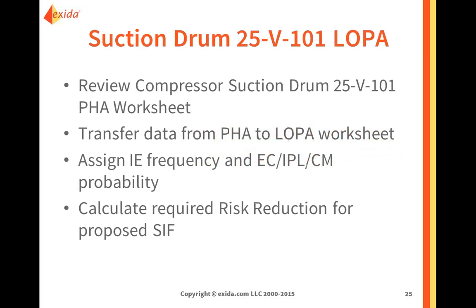So that's an example. Let's look at the layer of protection analysis tool in action. What we want to do is look at what I just showed on the slides: review the compressor suction drum PHA worksheet, then transfer the data from the PHA to the LOPA worksheet, assign frequencies, and then calculate the risk reduction for a proposed SIF. So let's have a look at that.